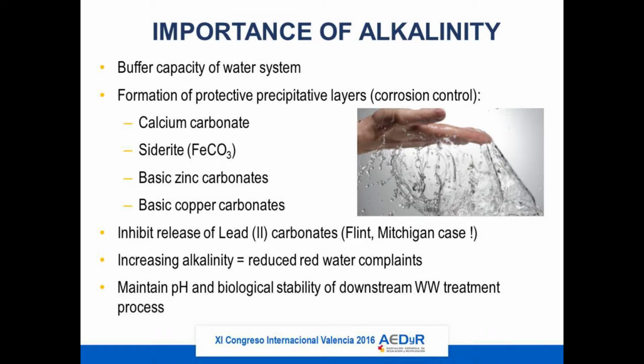So then, increasing alkalinity reduces red water complaints, as I said before. And then we also want to have enough minerals in the water, because most of this water goes back into our sewage treatment plants, and they also operate better if we have more minerals in them, the right balance of minerals.